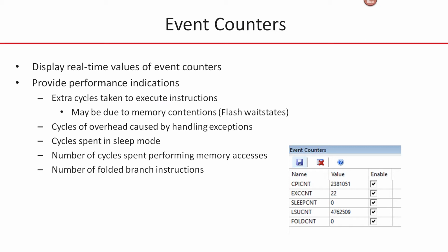So they'll show the number of cycles per instruction overhead. So this is kind of wait states where the processor hasn't been given code fast enough, and also execution overhead where we've incurred extra cycles in serving an interrupt. So this can give you some information about how efficiently your code is running on the processor. So it's useful to compare different silicon vendors' Cortex microcontrollers.